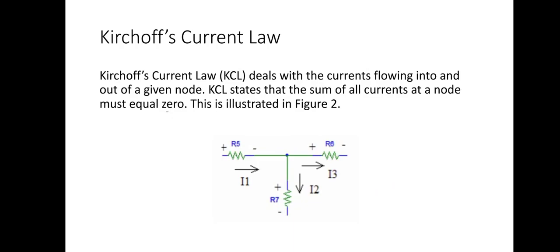An underlying assumption of KVL: no time-varying magnetic flux through the loop, otherwise there would be an induced voltage, also known as Faraday's law. Antennas are designed to pick up electromagnetic waves, and regular circuits often do so undesirably. How do you deal with antennas? Include a voltage source as a circuit representation of the induced voltage or noise.